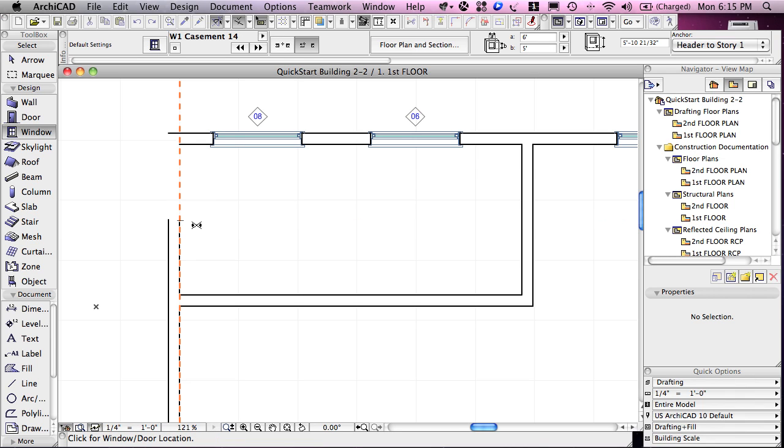Now when I'm putting the window in, you notice that it's putting in the corner at that point. So I probably want to switch to putting in the center. So again, many times when you're in the middle of an operation, you can see the preview and change it to get the desired result, in this case center, and then clicking to place the window.